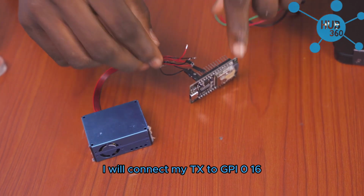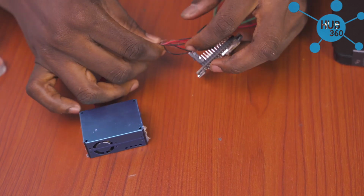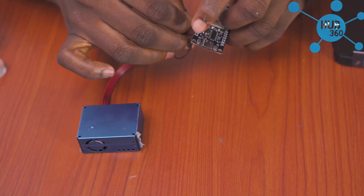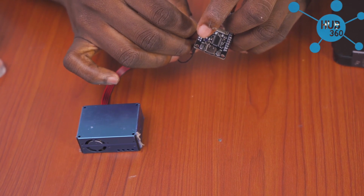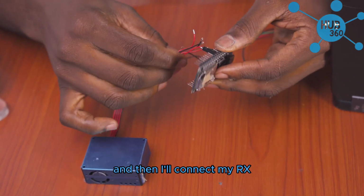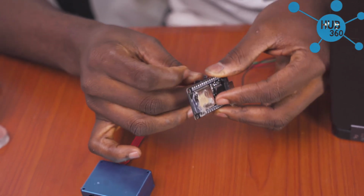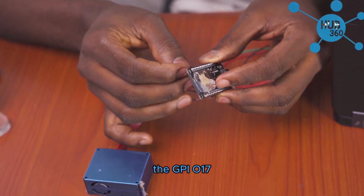And I will connect my TX to GPIO 16. And then I'll connect my RX to GPIO 17.